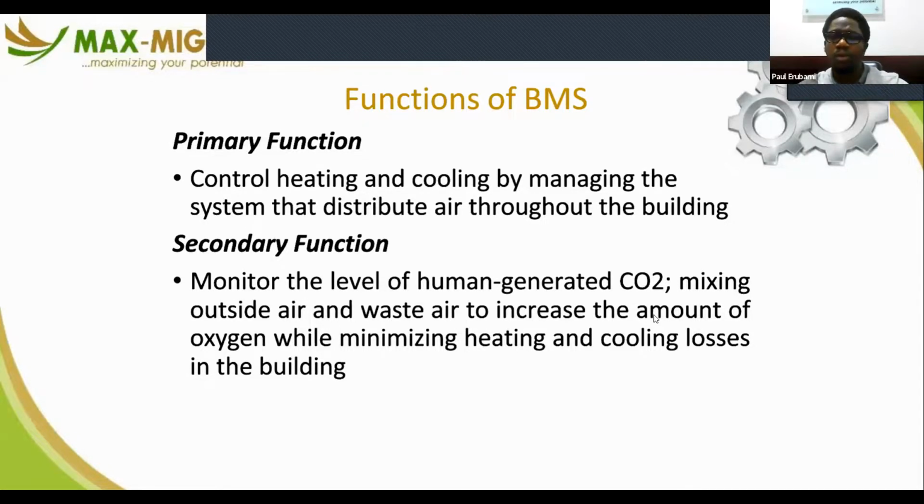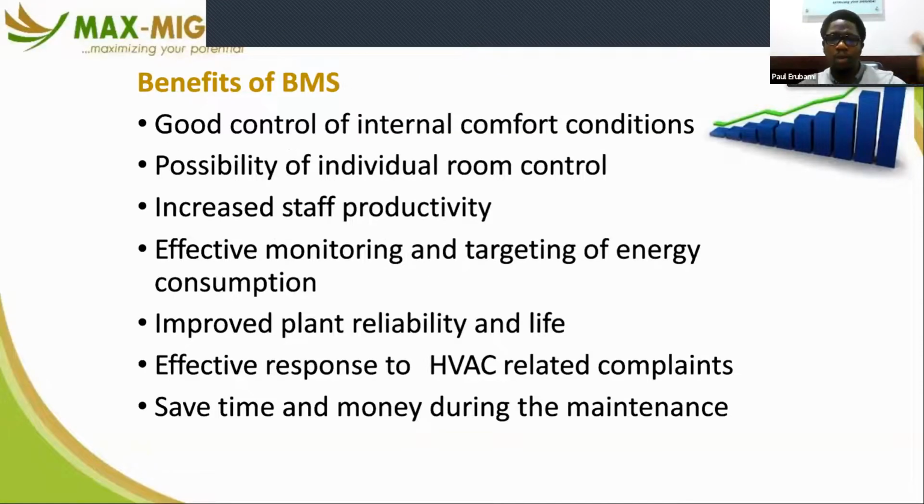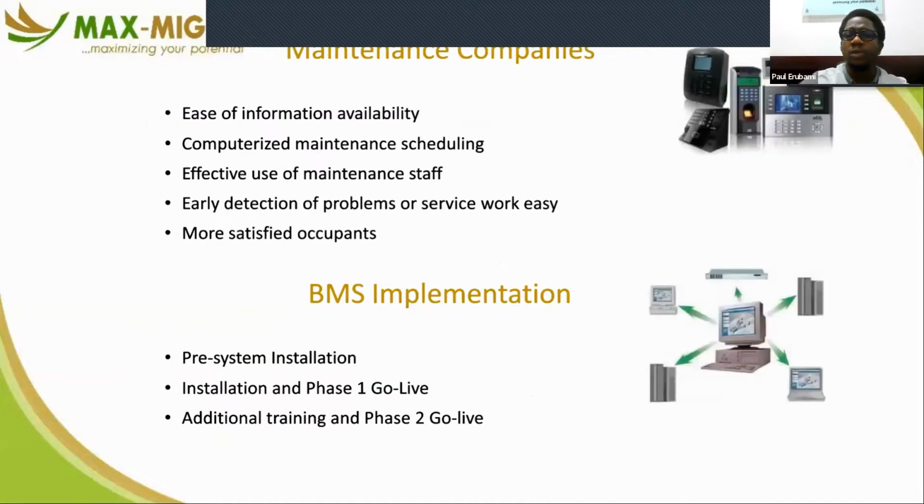So that's the whole idea. Control. I monitor and control. All right. So when people are complaining that it's too hot or too cold, I go and check. I see what the ambient temperature is. I look at the temperature of the chilled water and the air that the chiller system or the air handling unit or fan coil unit is releasing into that space, and then I make a correction by running some controls.